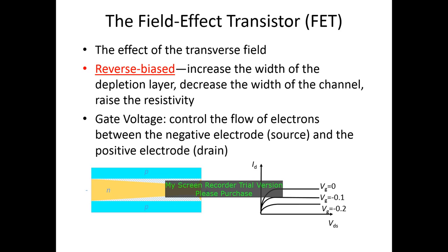The reason is that at high current, the voltage is very large, and then makes the region near the drain have more positive charge than the region near the source. Then there is an internal gate voltage of the field effect transistor itself, which causes the depletion layer to bulge into the channel. Then the current is limited at the highest current level.